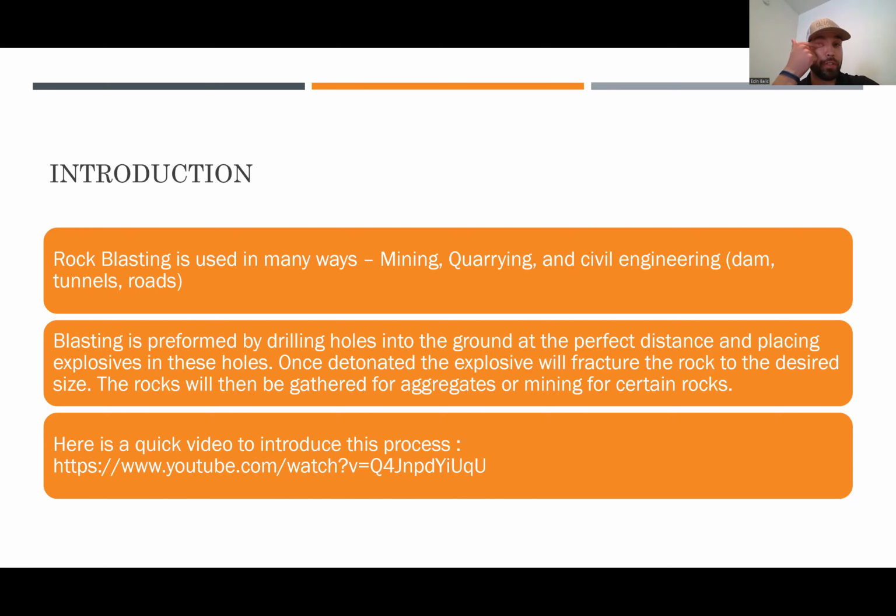Blasting is performed by drilling holes into the ground at the perfect distance and placing explosives in these holes. Once these holes are detonated with the explosive, it'll fracture the rocks to the desired size. Once we get to that, we'll use excavators and loaders and stuff like that to gather these aggregates and send them out where they need to go.